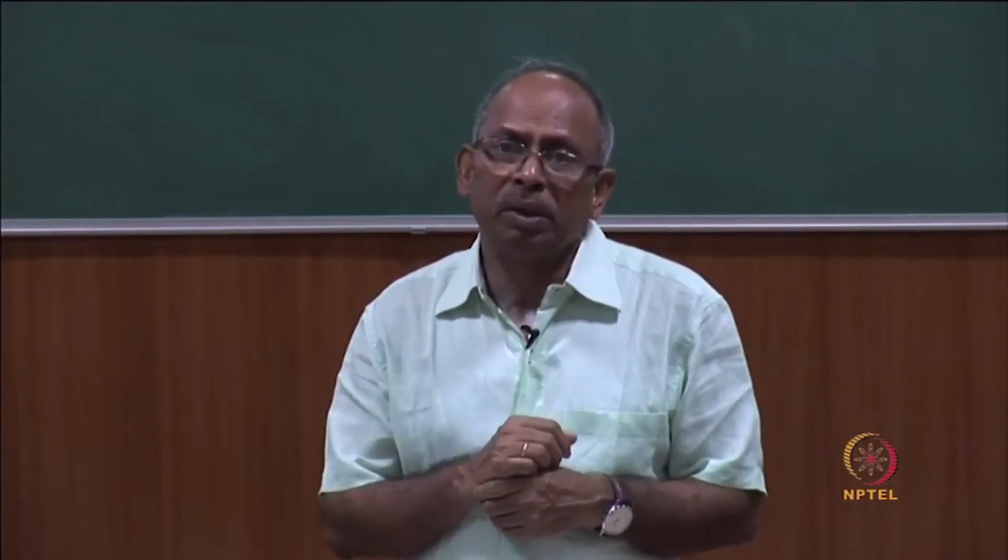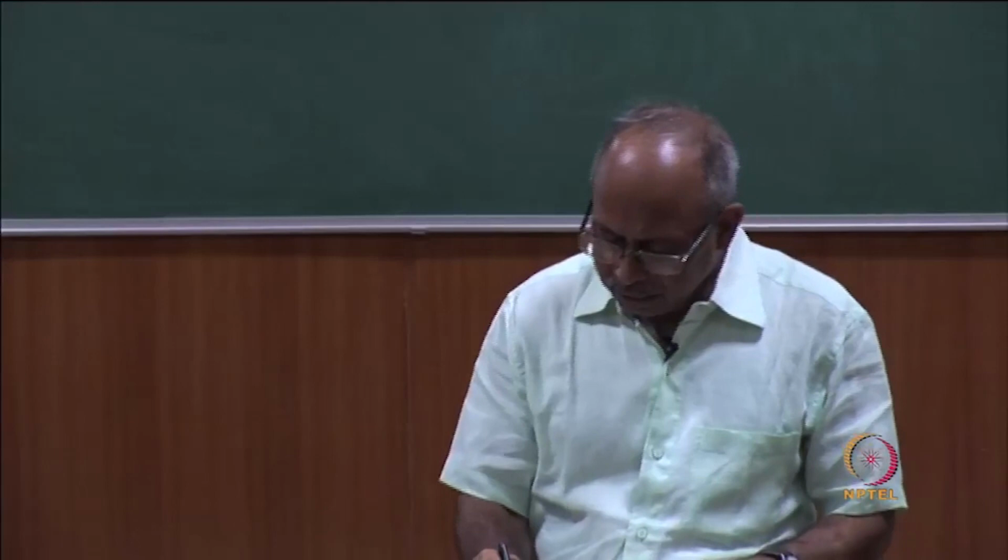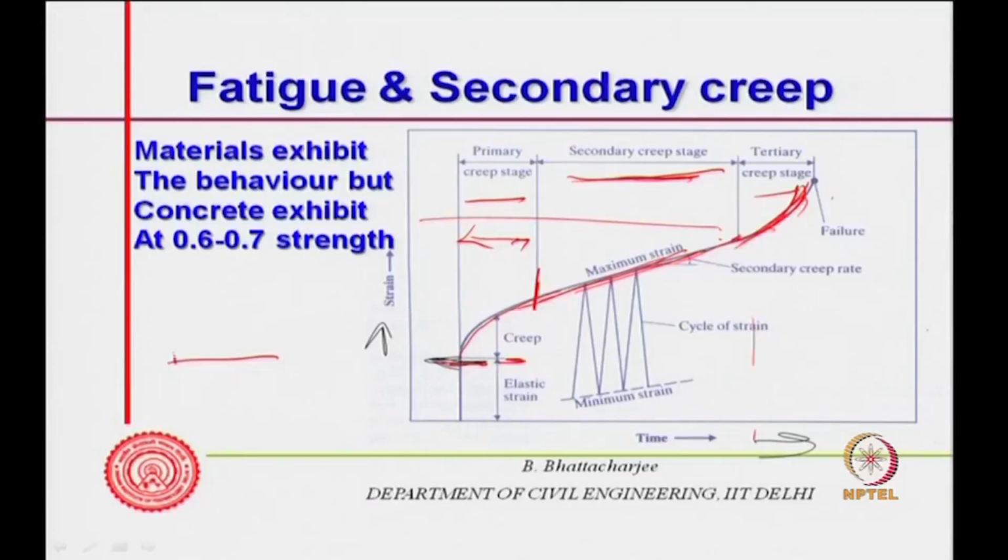I have a cycle of stress, let us say one cycle of stress going from maximum compression to tension again, and this finishes in constant time, or even sinusoidal or whatever. It is rectangular I am showing, but it can be triangular or something of this kind, some sort of cycle of stress I am applying. Now, you see this, let us say, is 10 seconds, then think of this being 10 hours or let us say 10 years. Now, one cycle in 10 years means there is a constant load, the load is sustained, but the value is changing.